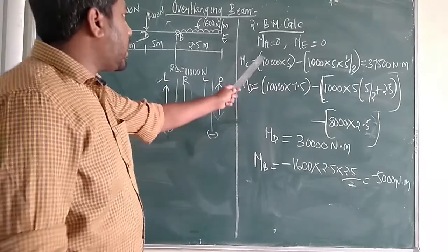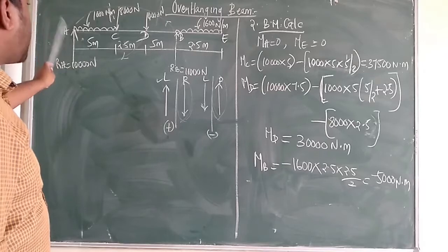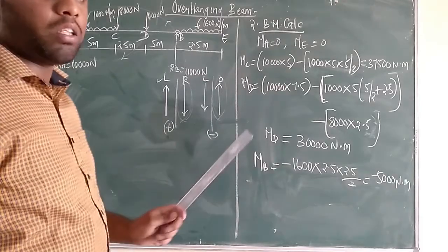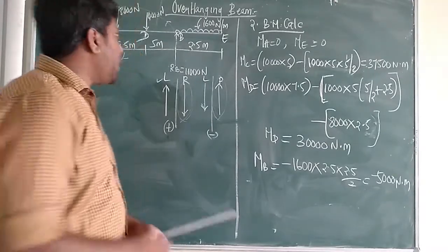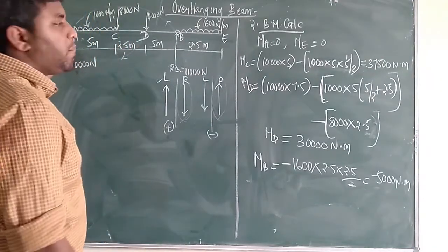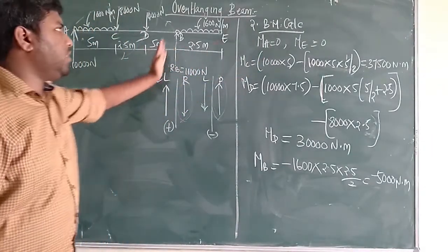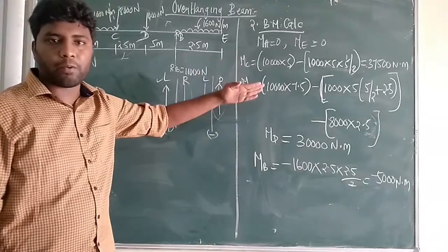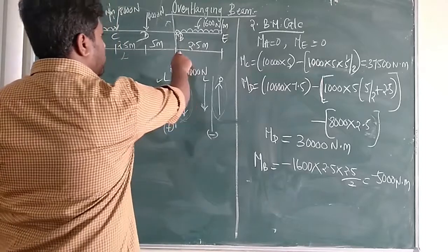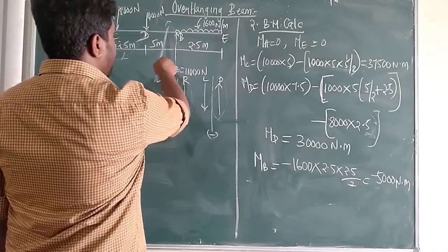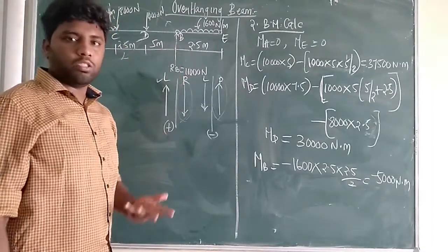Okay. So in the rules, if there is any support while calculating bending moment, at the support it is 0. All the supports while calculating bending moment will be 0. But here I am taking only moment at A is 0, but B is not 0 because after B some extension of beam is there. If this B is simply supported, if there is no beam extension and the beam ends at the support, that means moment at A is equal to 0, moment at B is also 0.